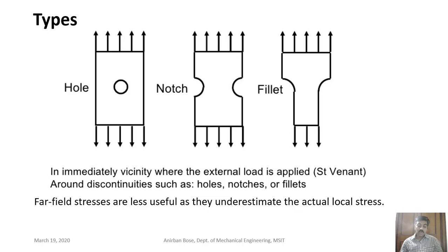In the theories of failure, what we have learned is how to apply the different failure theories to design a particular component. In doing that, suppose there is no hole in this plate and we want to design it, then what considerations will we make? We'll consider that under this external load acting axially on a plate, some stress will occur, and we'll see what the maximum value of the stress is.